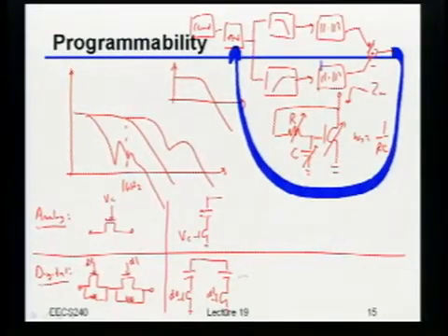Okay. Now, it turns out you can imagine if you're doing this and you have real data, if the data itself is always DC, then by definition, this thing is going to give you 0 output, even though maybe the equalizer was tuned correctly. So with a lot of these sort of tuning loops, you have to make some assumptions about what the characteristics of the data really are. So that's actually a great question. We're not going to spend a ton of time on how you really do this in this class. I'm going to assume that you know what the channel is, and so you can sort of design the equalizer. But in reality, this is absolutely an issue that you have to think about. It's a great question. Any other questions?